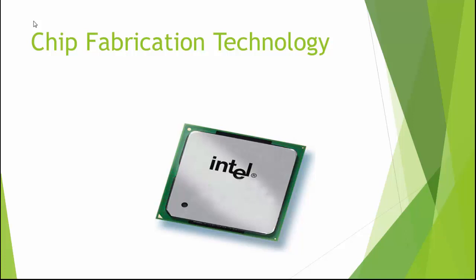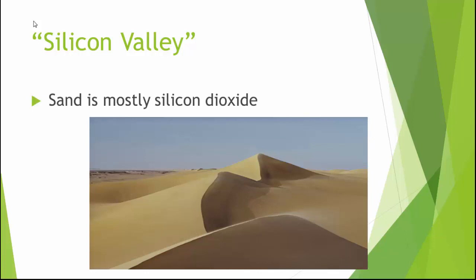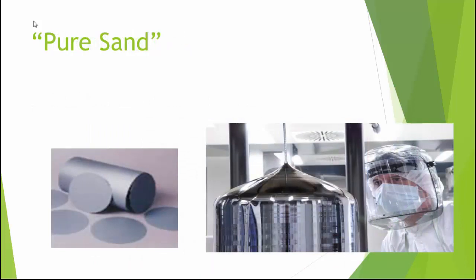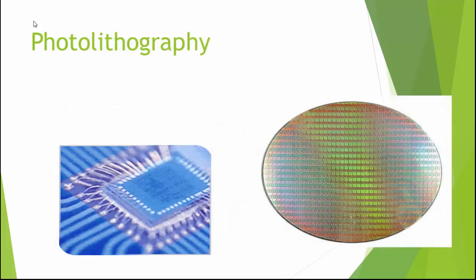Okay, so that deserves a lot more unpacking, of course. But hey, let's just start talking about the underlying technology, what they're made of. So the chips are essentially formed from silicon dioxide. So we can say in many ways, chips are made of sand. We can't make them simply out of the sand we find at the beach. We have to purify it greatly. As a matter of fact, there's an entire science around the purification of silicon dioxide into extremely pure materials that we can then use to make into the chips we've talked about.